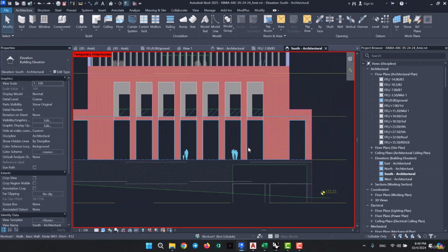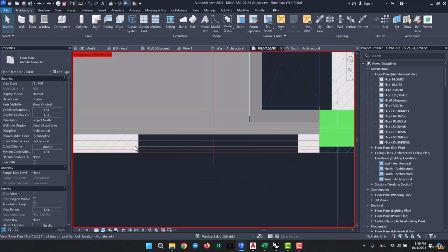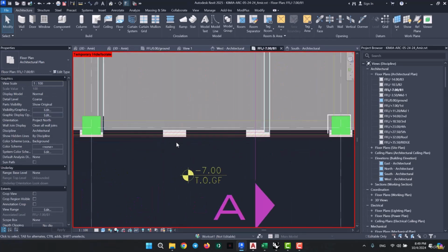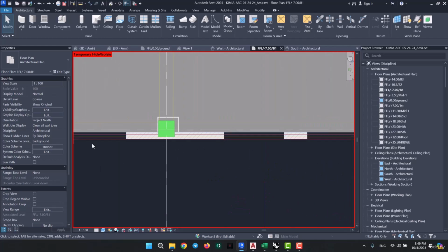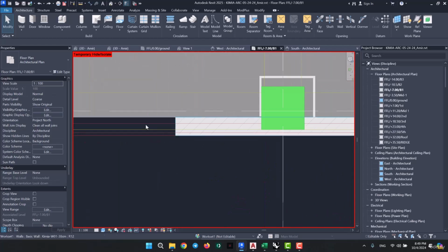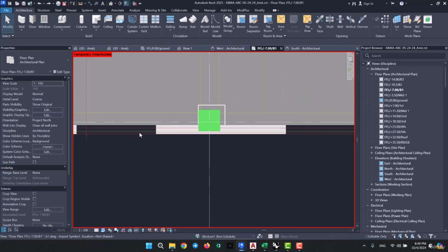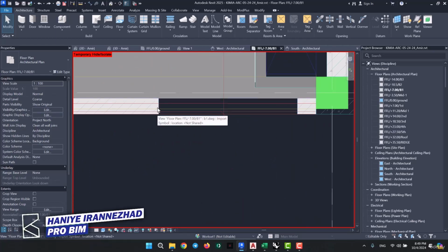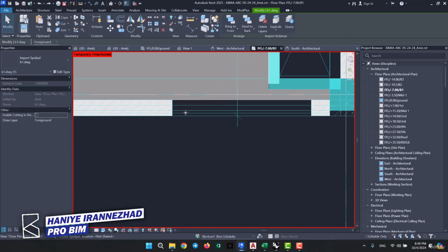So far we've modeled this wall for the basement level, and now we're going to go over here and fill all those rectangles we've just cut out with curtain walls. Essentially there will be glass panels here, and curtain walls are the tool to place them with. So that's that. The basement doesn't really have anything too complicated. You've also just watched how easy it was to draw. And if you take a closer look, you'll see it's all according to the CAD plan.